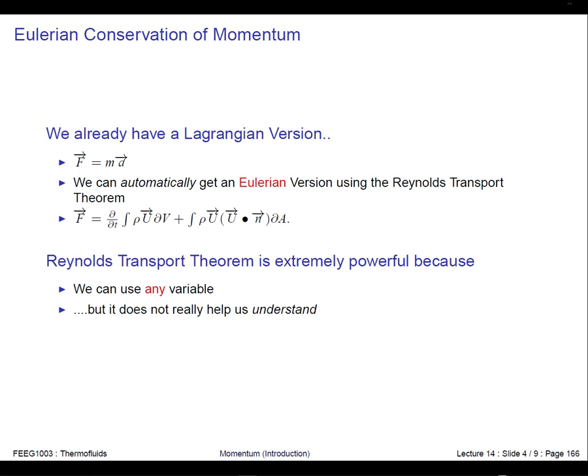And if you think of your jet engine as a control volume, there is a net force on that jet engine. There is a net force on the support connecting the jet engine to the ground. Okay, so this is the same way. So this is why the momentum balance over a control volume, based on the net flux or the net flow of momentum into the control volume, doesn't have to sum to zero. Okay, so this is a little bit different to mass conservation.